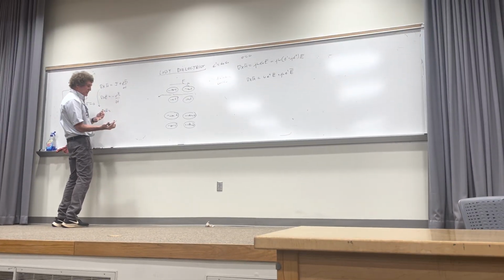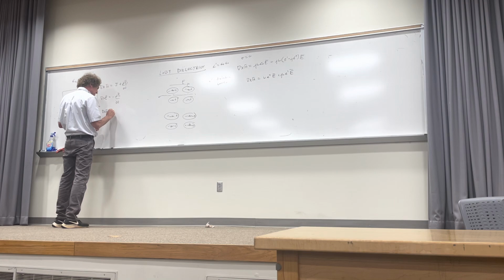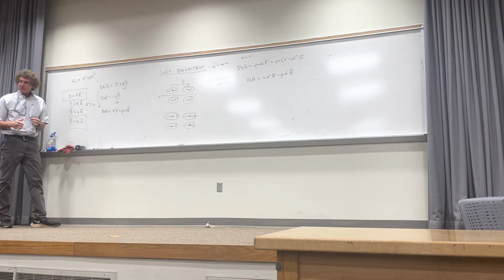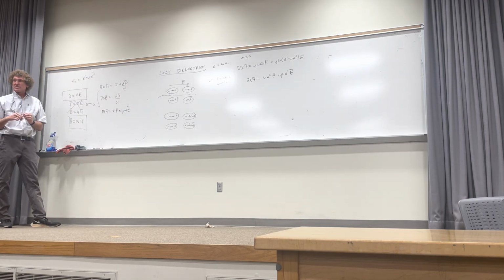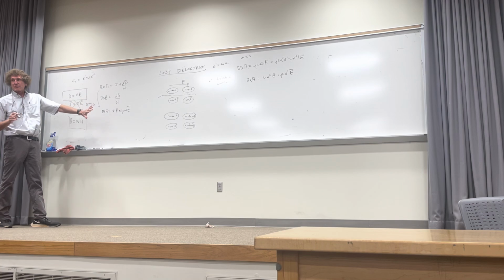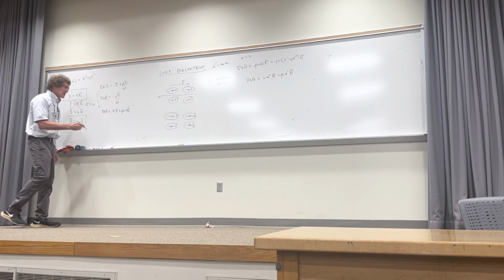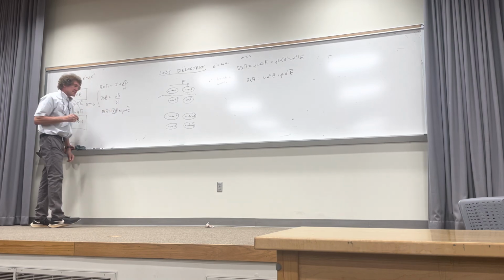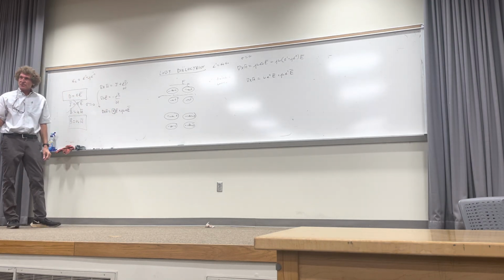I'm going to go to the frequency domain, and then I'm going to show you what you would have: sigma E plus j omega epsilon E. You all follow me on this? I'm going to the frequency domain, and I'm going to replace d/dt by j omega. I know I said sigma 0 in perfect dielectrics. That's true, but I'm trying to build a case of how come that's a loss mechanism. You see how the coefficient of E by itself is sigma, and that accounts for the conduction losses there. You all see this, class?